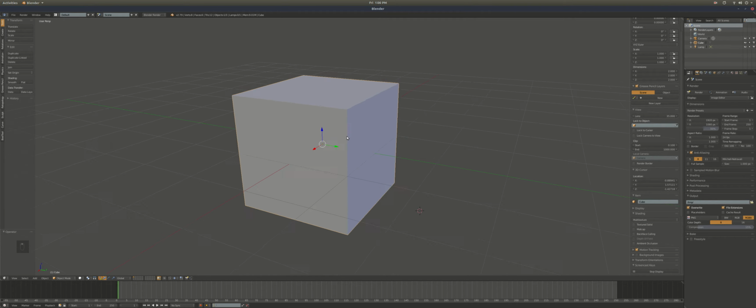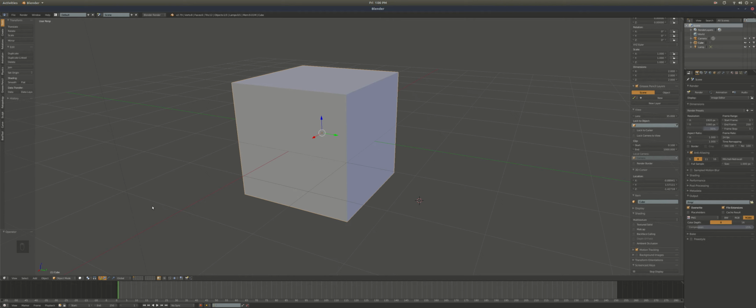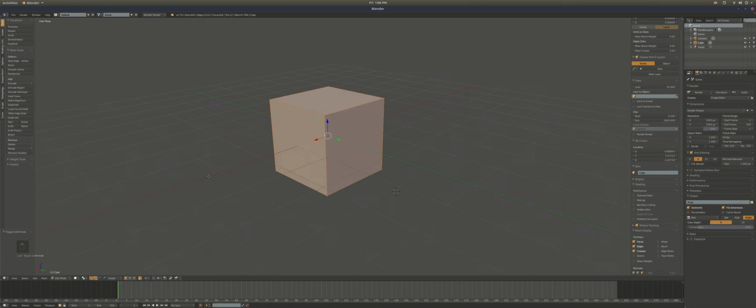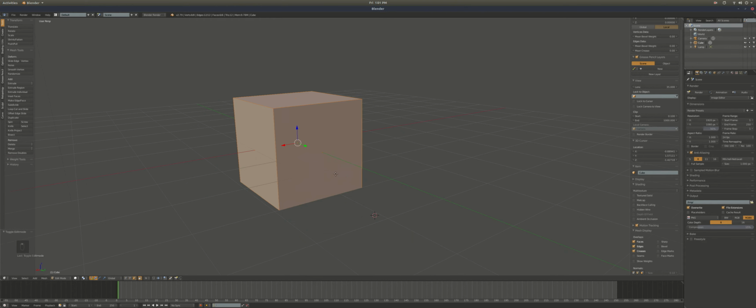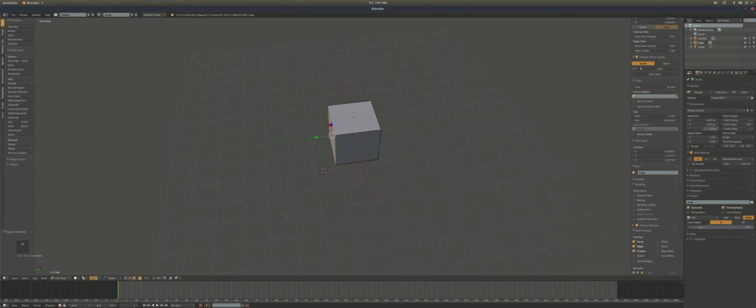Now, one thing that is important is modes. So right here, this is where you find it in the panel, you're going to see object mode, edit mode, sculpt mode. That's your interaction with the mesh or the object in front of you. So if I hit edit mode, then I can see the vertices and the edges and the faces, which are all going to be right down here. Vertices, edges, and faces. Right now it's on vertices, but if I click face, you'll see this little square down in the center of the face. You just right click on it and you got it.